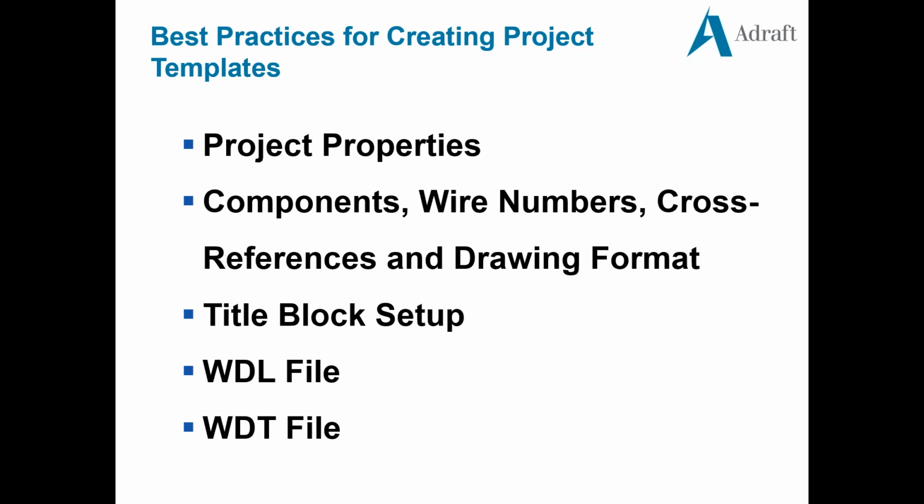And the same with the cross-reference standard and the drawing format. These all go into project properties. And then the title block setup is included in the project. That's why we create a template project in the first place, because once you create it once, you'll never have to create it again. It's just literally a copy from one project to another. Included in the title block setup, I'm going to discuss the WDL and the WDT files.